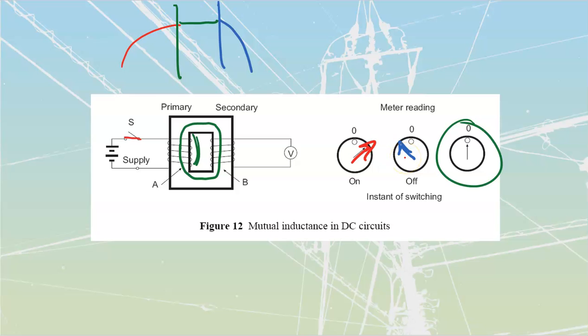We'll refer to these as being a primary side and a secondary side. The primary side has got nothing to do with what's high voltage and what's low voltage. Primary just means that's the side that we are feeding electrical power in. The secondary side is going to be the side that we are taking electrical power back out of. And it actually goes through a bunch of really fantastic changes on the way to get there. Really, what we're seeing is this change from electrical energy to magnetic energy, and then from magnetic energy back into electrical energy.